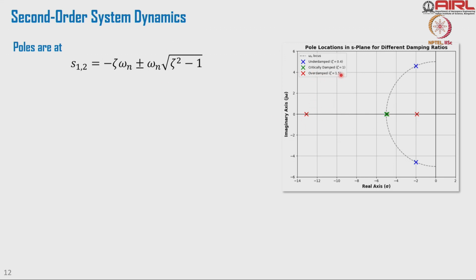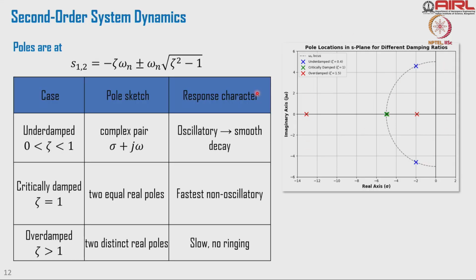This becomes an overdamped system, zeta will be very high. If one pole sits exactly over the other, then what will happen? Or a pole on the imaginary axis becomes an underdamped system, which means it will have overshoot and oscillation. So, by looking at a pole's location, I can interpret how the response is going to be.